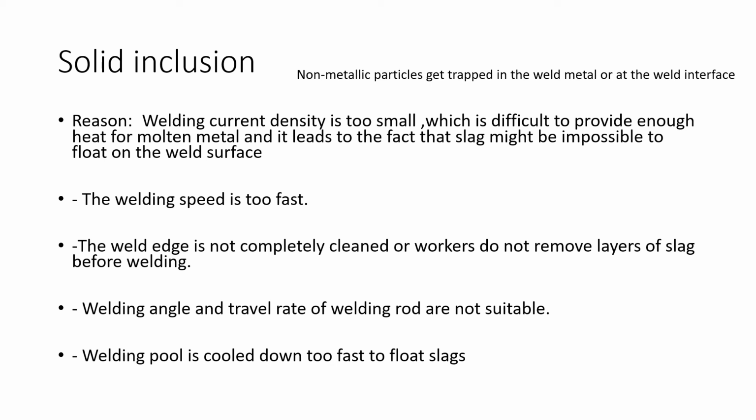So the opposite should be practiced. If the weld edge is not completely cleaned, then also it can occur, so we should see that it is properly cleaned. Then the welding angle and travel rate of the welding rod: if they are not suitable, solid inclusion may occur. Then if the welding pool is cooled down very fast, as I have told earlier, there is a lesser chance for the non-metal to float. Therefore, solid inclusion takes place.